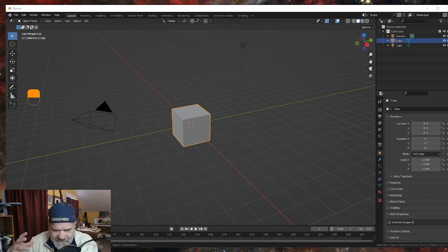Do that stuff that's not fun to figure out in Blender, but you just want a 2D CAD system in order to do that. Then you want to take that drawing out of your CAD and import the DXF into Blender. Now, we're going to do that today. I'm going to show you.